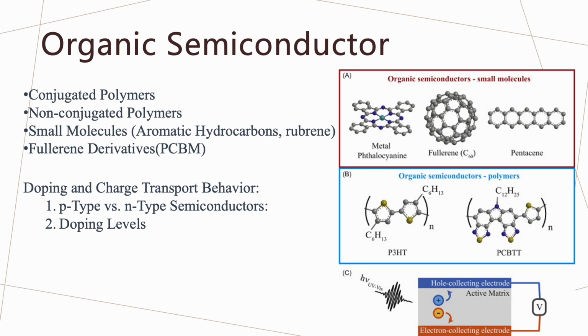The selection of organic semiconductor is also a very important process for fabrication. Generally, N-type organic semiconductors show lower device performance compared with their counterpart P-type organic materials. Conjugated polymers offer good charge transport properties, but their performance can vary based on the specific polymer structure. Some non-conjugated polymers are used as organic semiconductors in OFETs. They may exhibit lower charge carrier mobility compared to conjugated polymers, but have unique properties suitable for certain applications.